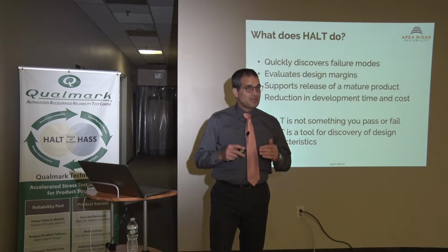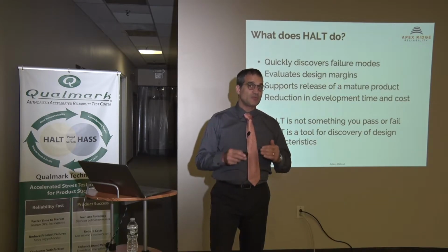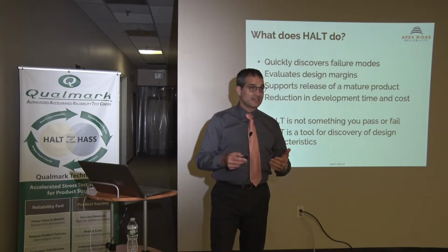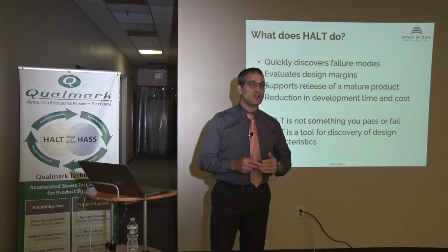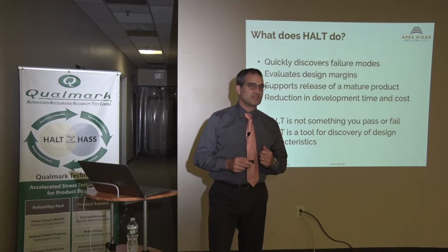So it's hard to get people to change how they think to understand that you're going to drive the product to failure. And where this pushback occurs is when you describe to them what you're going to do to their product and they say, that is unfair. Why are you going to do stresses so far beyond how it's used? Why are you going to vibrate it to 50 Gs when this thing sits on a shelf?